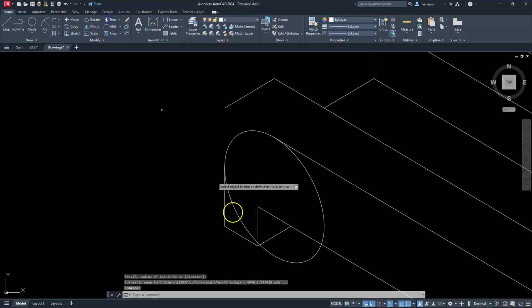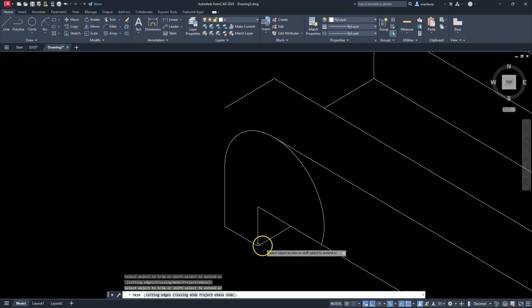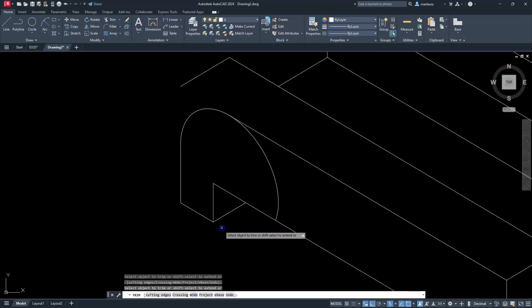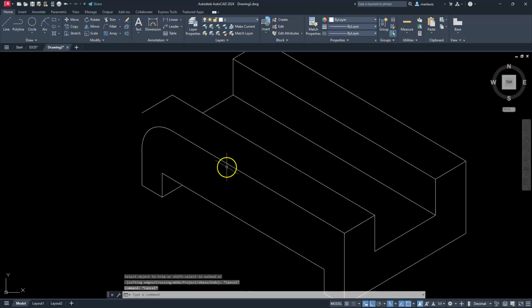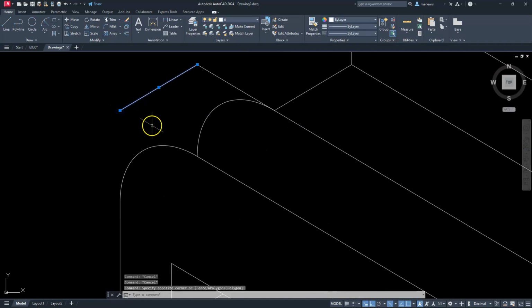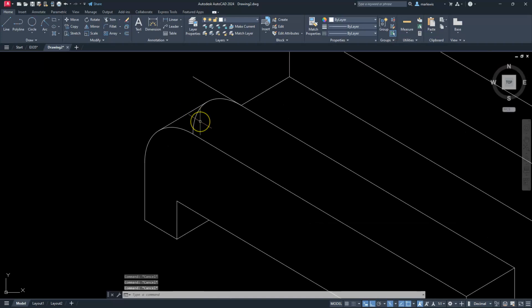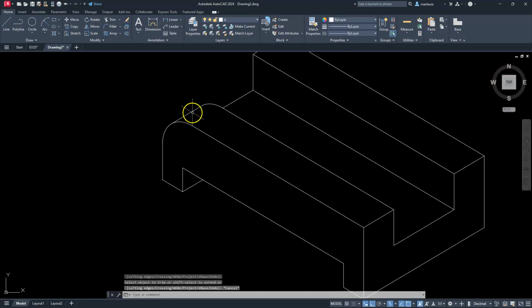Alright, let's trim off the rest of this. So I'll go to trim, take away, and I do have an extra one there. Alright, once I have that trimmed off, I'll copy this circle. So let's use copy, select my arc, enter, from this endpoint going to that endpoint. Let's move this line here. So I will select it, go to move from this endpoint, and then put it on this quadrant. Alright, then finally we can trim off some stuff. So TR, and then trim off that portion.